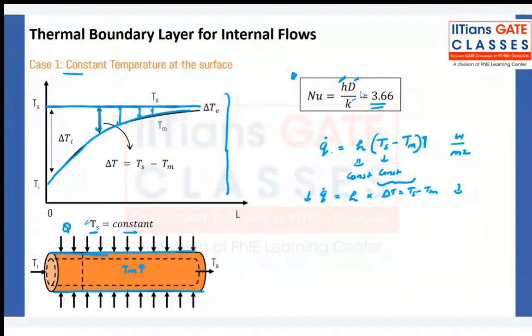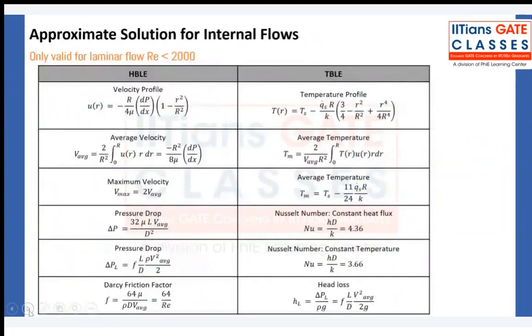Chalo. So this is kind of the summary of what we have done today. Again, internal flows, Reynolds number will be less than 2000. Turbulent flow, what is the Reynolds number? Can you tell me for turbulent flow in internal flows? Reynolds number for turbulent flows, yes, is greater than 4000. And in between it is transition flow. Okay, transition from laminar to turbulent.